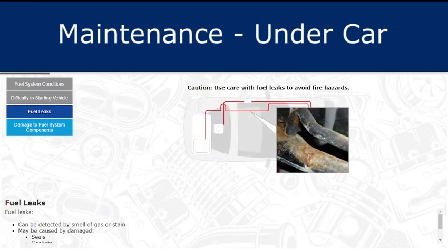Fuel leaks can be detected by the smell of gas or a stain. Fuel leaks are caused by damage or corrosion to seals, gaskets, or fuel lines. A damaged filler cap may also cause leaks. Caution: use care with fuel leaks to avoid fire hazards.